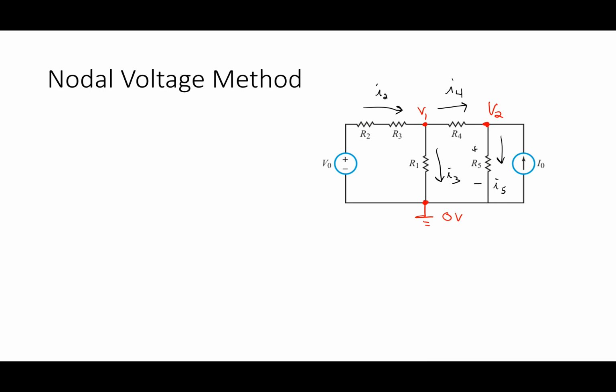Why do we use the term ground? Anybody know? Why isn't it connected to, if you follow that wire, isn't there a big rod that goes into the ground? Yeah. So if you go to your house, what they do is they will drive a rod into the ground, for the negative terminal, right? So coming into your house is basically a voltage that is AC, right? And the negative terminal of that voltage is driven directly into the dirt. And that dirt is the reference node. It's called 0 volts. We call it ground because it's literally in the ground. Okay. And that's why we use that terminology.